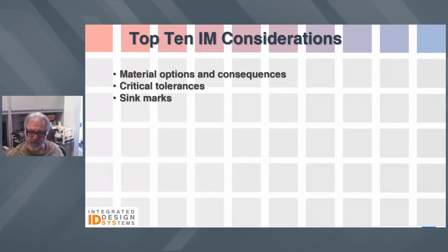And in all these cases, it's always wise to reach out to a molder that you trust or that you're dealing with in your supply chain and confer with them throughout the design process as you start refining these features. In many cases, it's difficult to predict how parts might fit together, especially when the tolerances are very tight. And in these cases, it's always better to design the parts to be slightly loose fitting, which means that the mold has extra steel in it. So the parts are a little smaller than they should be, depending on the features, of course. And that's what is implied by this term steel safe. It's easier to remove metal in a tool than to weld it in and start to remachine it.